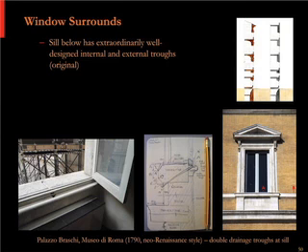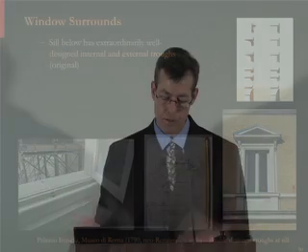So they have actually two internal drainage systems built into this window. So on the photo at the lower left, you can see there's kind of a line where the window would close. That's a trough, and it's in the travertine sill, and then it makes a T shape heading out to that little hole. So that's an outside drainage trough. So water that runs down that window is funneled there. It had a nice slope getting the water all the way out to that drainage hole.